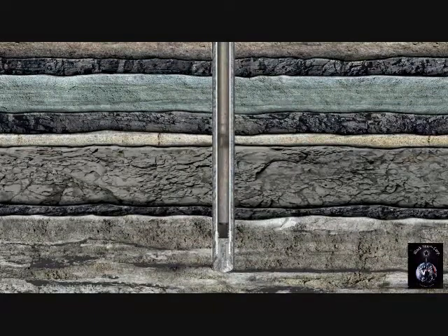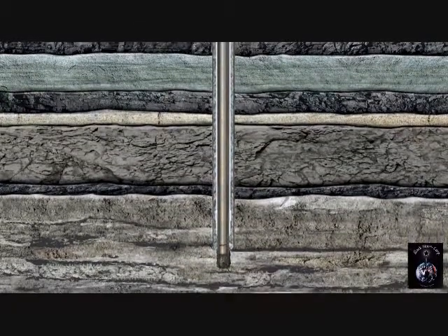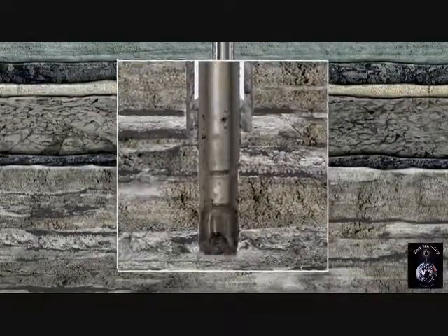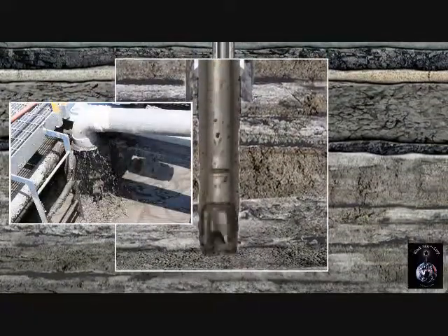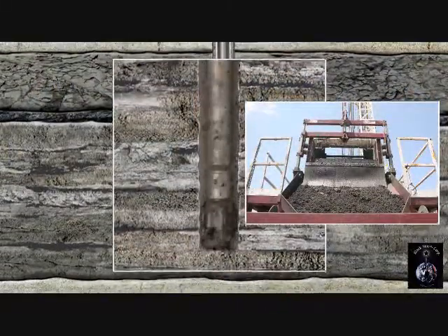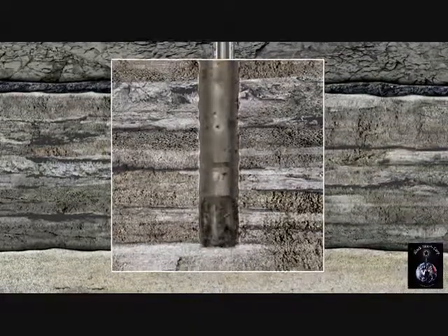Once the casing cement has set, drilling of the intermediate section of the hole continues by drilling through the wiper plug, shoe, and cement at the bottom of the wellbore and on toward the targeted zones. Throughout the drilling, a mixture called mud is pumped down into the well through the drill pipe. The mud serves to keep the drill bit cool. It carries the cuttings to the surface and provides hydrostatic pressure, prohibiting formation fluids from entering the wellbore.